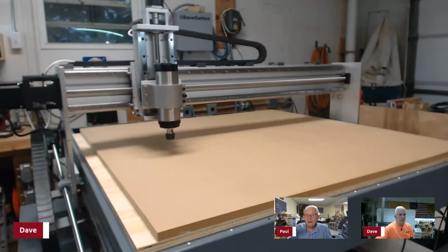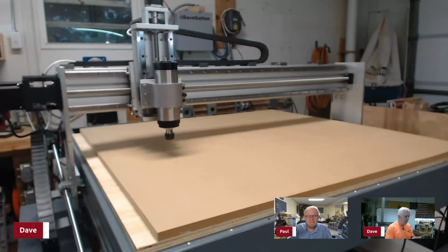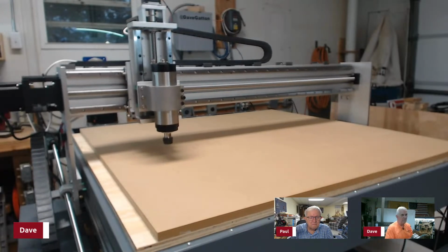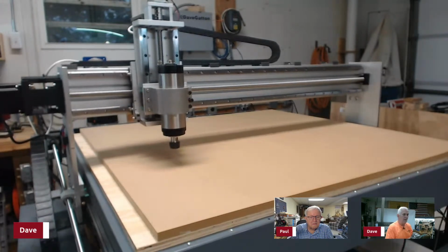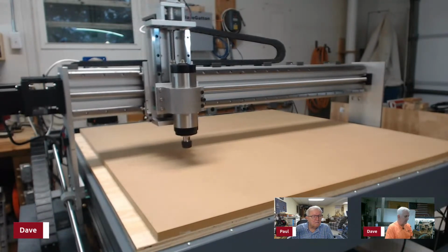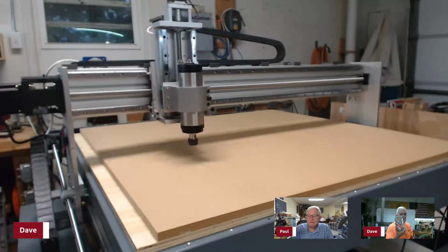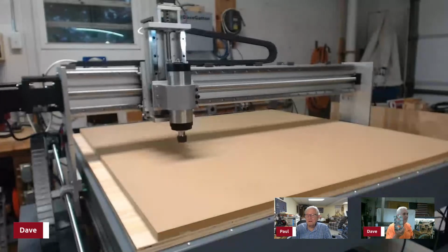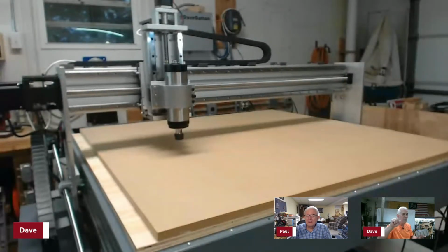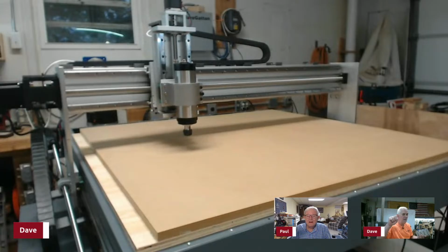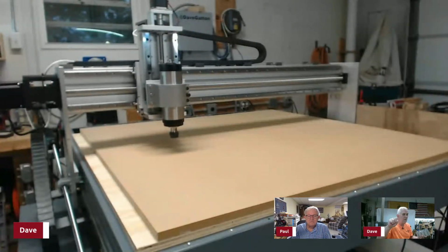Now, did you just mark it and cut that with a hacksaw, did you? I was so worried about cutting this because I'm like, is my little old Ryobi saw going to be able to handle this? And I measured it off, double and triple checked my measurement, and went around there with my Ryobi miter saw, and it went through it. I didn't go very fast. I'd cut down a little bit. When I'd hear the saw starting to slow down, I'd just kind of stop and let it catch back up and then go down a little bit more.